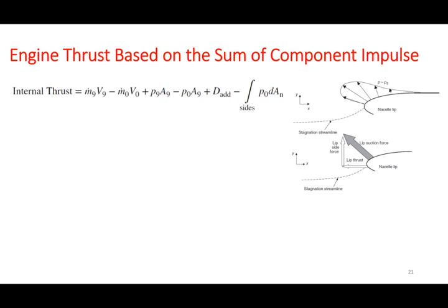We also have some other forces that are present here, as we have discussed. We have the nozzle force, which is the force that is being applied to the outside of the jet engine. That includes the viscous forces and the pressure distribution, so the shear forces and the normal forces. And there is a pressure distribution that's going to change, as you can see in this picture here. So we have to take that integral with respect to the changes in area, and we have to add the viscous forces as well.